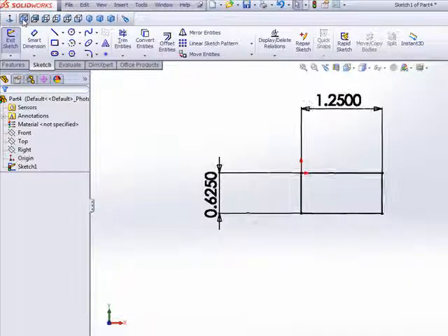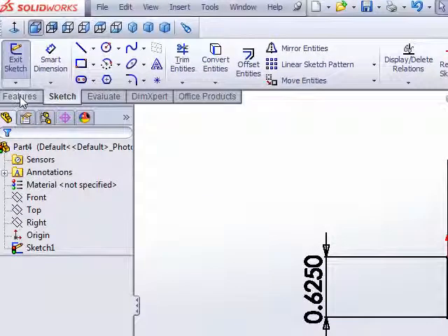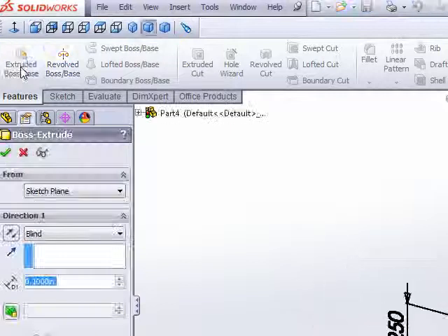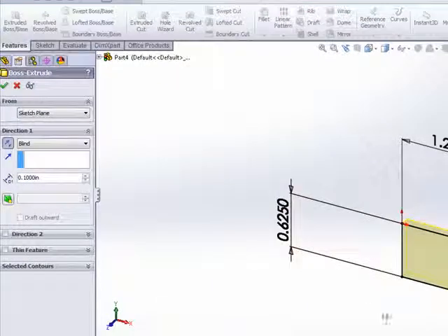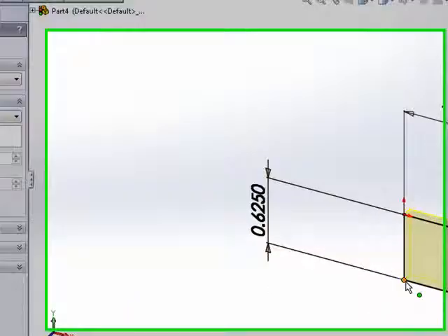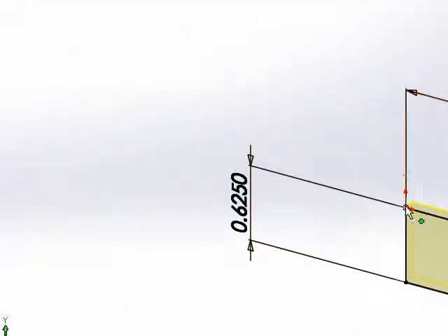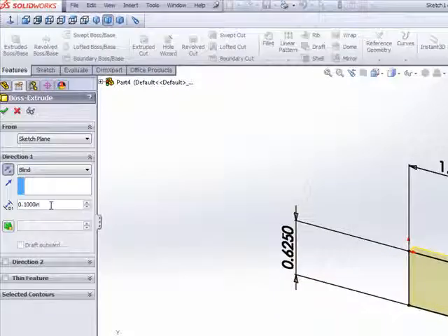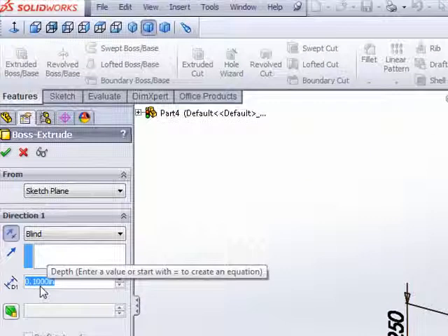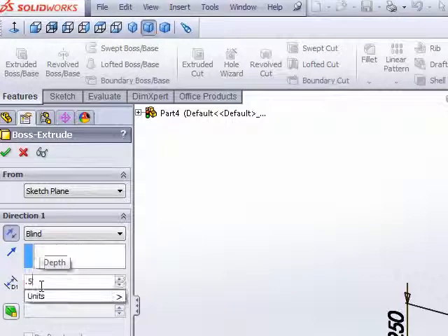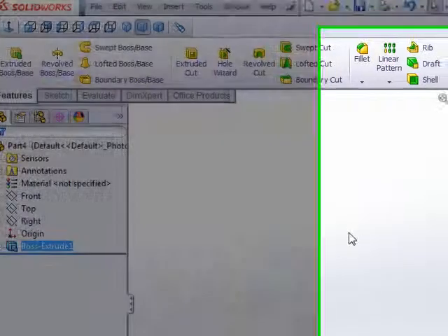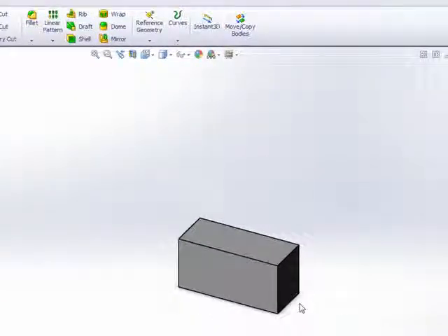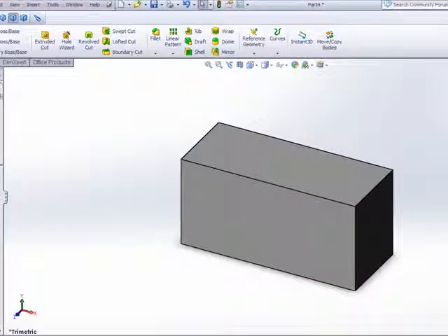I can go home and I can at this point extrude that. I like to extrude away from my Z0. XYZ0 is now in this corner. I'm sorry, this corner. You see the little indicators. And I do know that that height is 0.512. Now I've measured some bricks, and so I'm just going by the classic brick. I've just created my basic block.